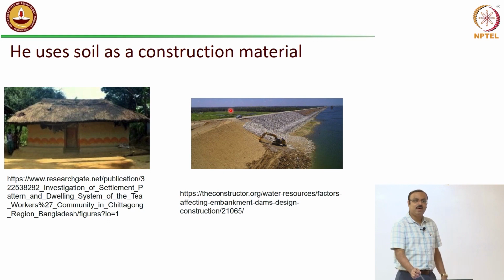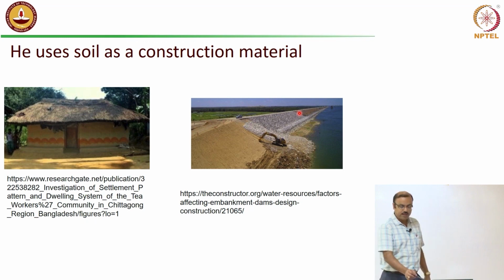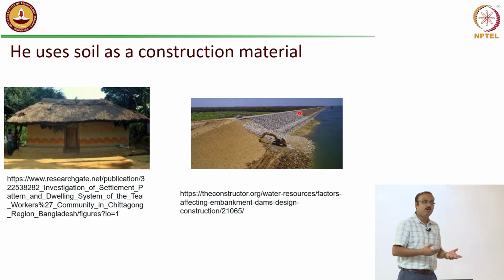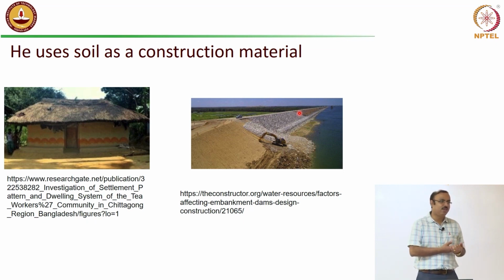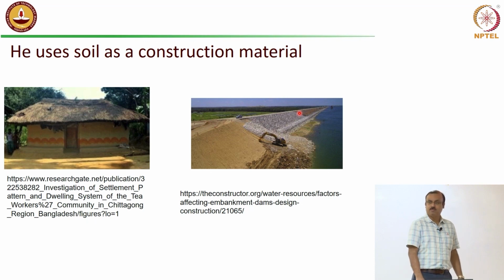Well, there may be cases where the water rises beyond the height of the embankment, and at that time it will flow over, but that is an extreme situation. In general, what we do is, under a high flood situation, we determine what the height of the water would be. We keep some 1.5 to 2 meters on top of that, and we create the embankment from soil. Now, certain properties of the soil will of course be evaluated to choose the material. Not all soil, whatever is available locally, can be used. There are certain characteristics required for soil to be selected as a good embankment material. This is where another major infrastructure, involved in the day-to-day life of the people, comes in, is it not? Everywhere we see this, we call it earthen embankments.